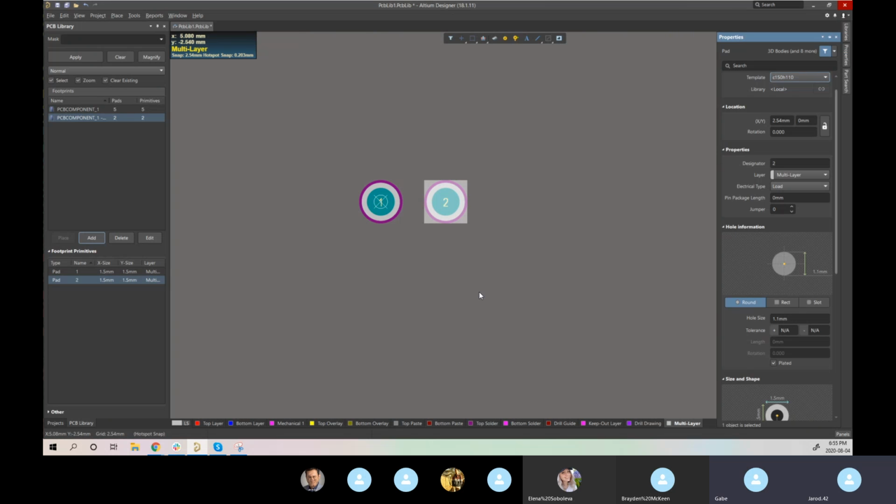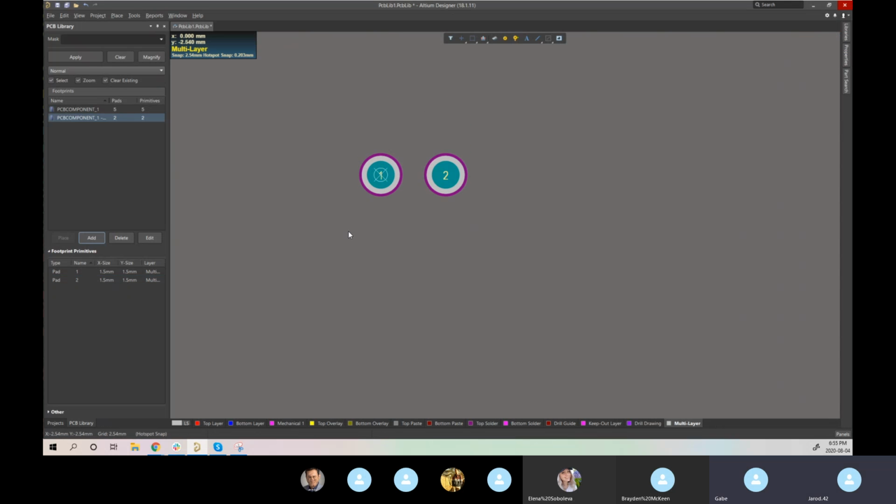Yeah, I actually made the mistake of not plating the other day, and Altium gives you a DRC error. It throws an error. Yeah. I almost always just glance over that, so I've never. Yeah, it's supposed to be default on. I don't know why mine were off, but yeah, it's important to have that checked.